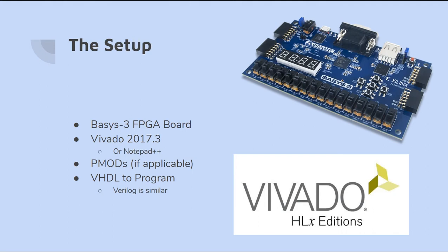The actual language we'll be using is VHDL, as I mentioned earlier. VHDL is a hardware description language. It's different from a programming language. A programming language is how you make software applications, and so on and so forth. But hardware description is specifically describing exactly how a system such as the Basys 3 board or an FPGA is designed to work.